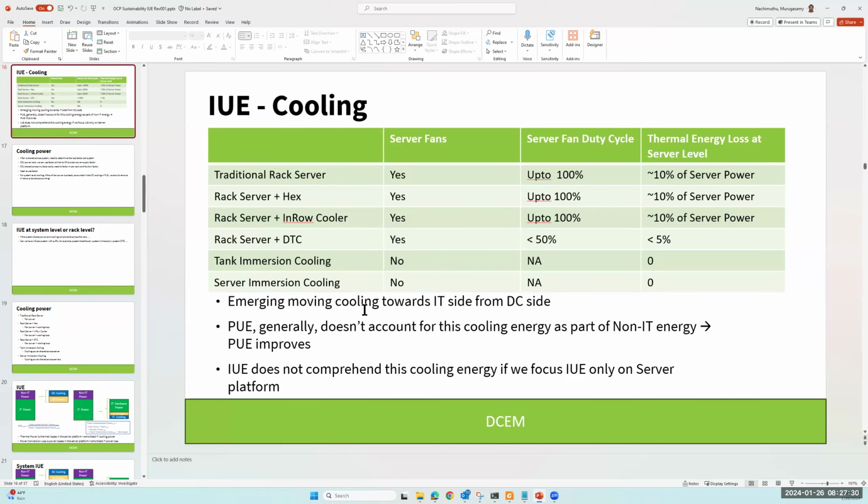Well, how I did it was in my carbon index determination, I put together a traditional cooling method for, say, a rack with a 34-node system, or 48, or 42. Then I calculated what the PUE is. Then I took the same thing and put it into immersion cooling, and asked what the carbon footprint emission is. It came to 15 to 22% lesser carbon footprint compared to method one. So that's how I rolled it up.